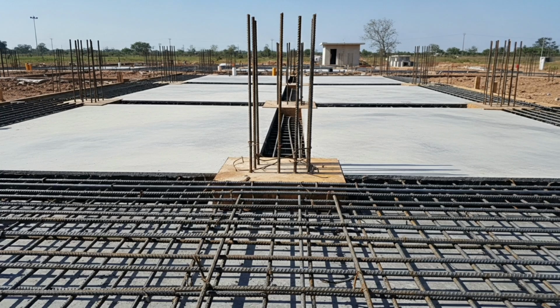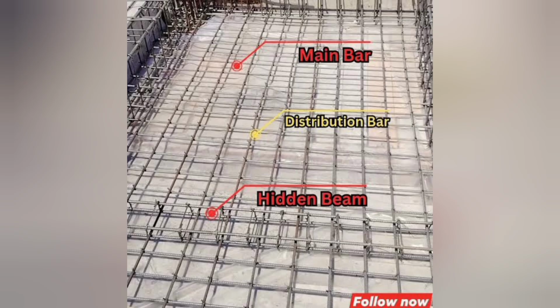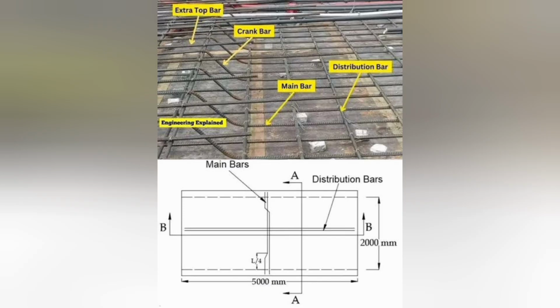sagging moments. A pro tip for site engineers: always check the placement of the reinforcement. In a two-way slab, the bars in the shorter direction are placed above the bars in the longer direction at the intersections, as the shorter span carries a slightly greater moment.